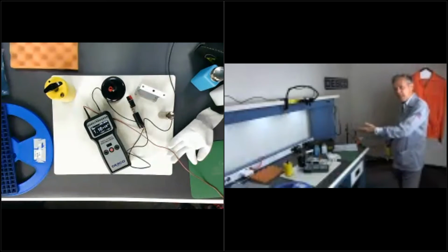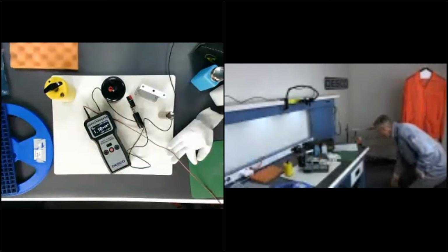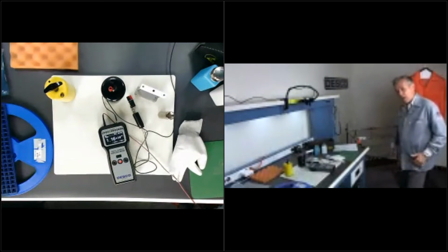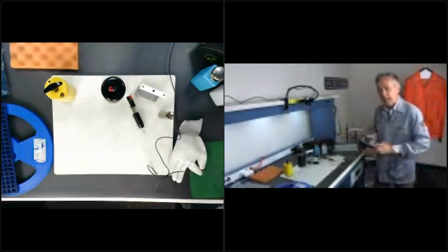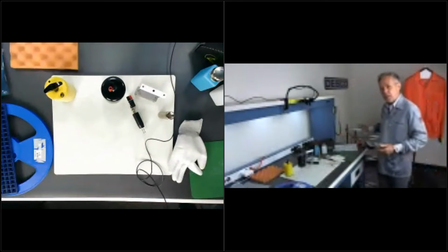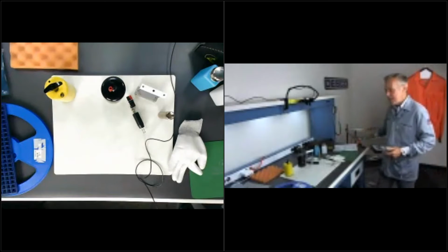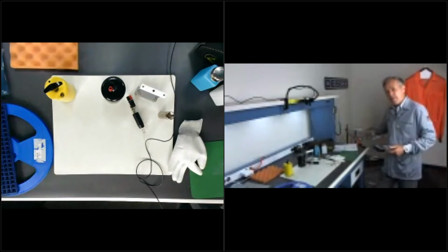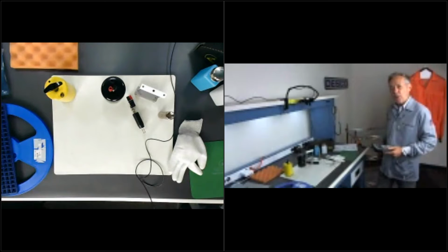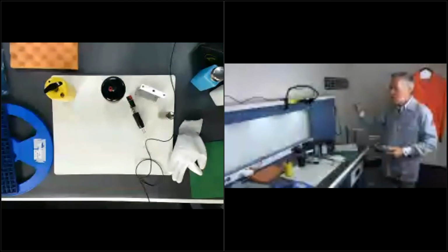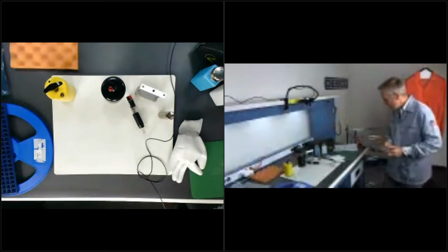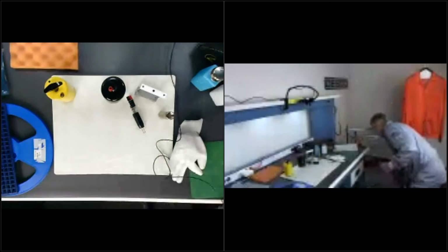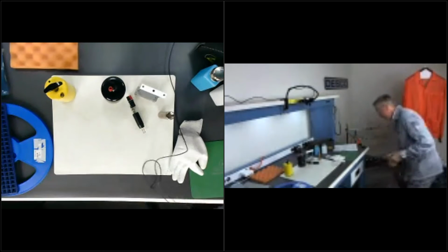So again, I've got my standard universal AC ground. Now I'm going to put my 5-pound weight on the floor. And it's important to understand, a lot of people make this mistake when they're checking their carts or when they're checking their floor, specifically carts. They'll put their 5-pound weight on the cart, and then they'll put the other 5-pound weight on the floor. That's not resistance to ground. Resistance to ground is the ground wherever your ESD ground is, or where that floor is grounded to. So I have to put that back here where you can see it.